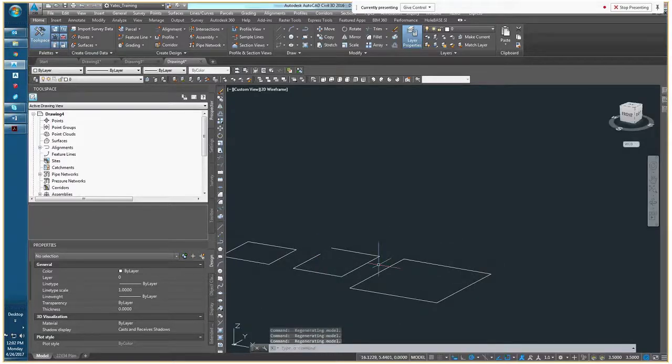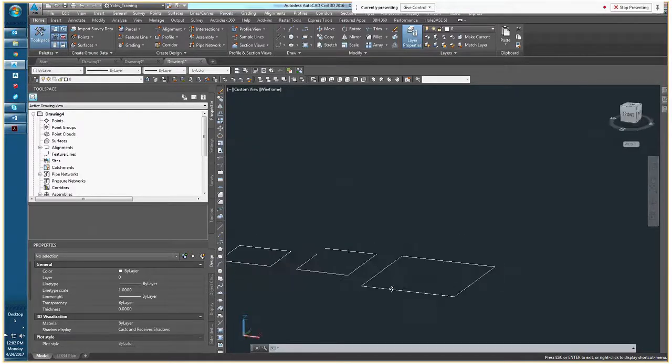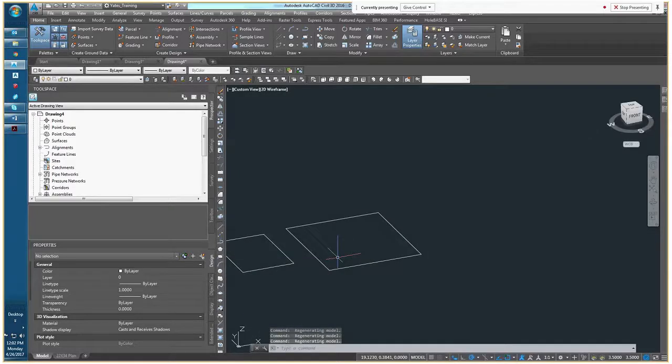If you're working off of a laptop or an older desktop and you have a lot of objects in your drawing, I don't recommend doing this. Free rotate will certainly crash your computer if you've got Civil 3D surfaces and other complicated objects going on. But with this simple amount of line work, I'm able to free rotate pretty freely without messing up anything or crashing the program or my computer.